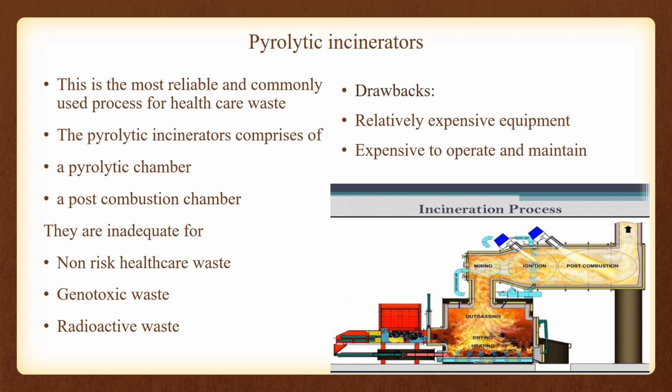Pyrolytic incinerators are suitable for what type of waste? They are suitable for infectious waste, including sharps and pathological waste, and also pharmaceutical and chemical residues. They are inadequate for non-risk healthcare waste, genotoxic waste and radioactive waste. Everything has its own positives and negatives, so what are the drawbacks? The drawbacks of pyrolytic incinerators are that they are relatively expensive equipment, expensive to operate and maintain, and well-trained personnel are required to work with them.